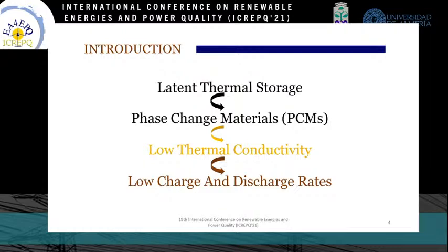However, the main drawback of latent heat thermal energy storage systems is the low thermal conductivity of current PCM. This weakens thermal conduction in these systems, resulting in considerably long energy storage and recovery times. To increase the thermal conductivity of PCM, different studies examine different approaches, including the expansion of the heat transfer zone using thin metal matrix, carbon nanotubes, and the use of nanoparticles.